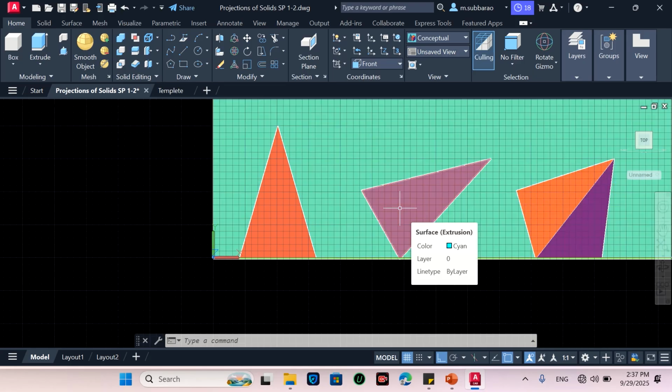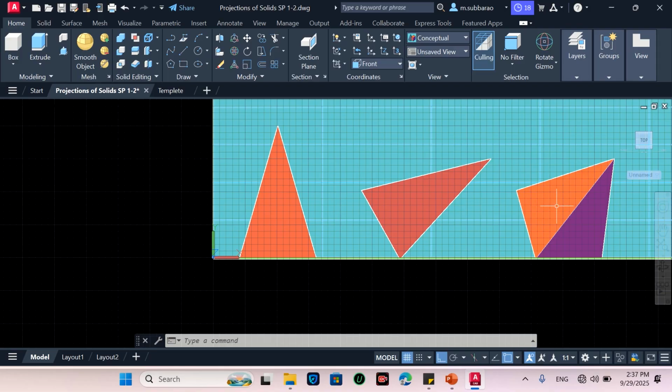Earlier the triangle was different, now this triangle shape is different because the front view is changing here. But the only thing is the height from the horizontal plane or XY line in this front view is the same. Apex height is the same and this height is the same because we are drawing the horizontal projections here. So with that we are able to draw. Likewise, we can easily imagine, when you are rotating the actual solid, how the shape of the solid is changing in each view.